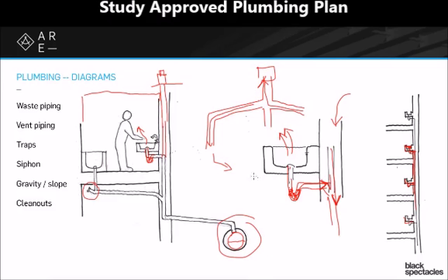that whole thing out. So at the bottom of all the verticals, at any major 90-degree turn or any other kind of strange shape in the pipes, even pipes that are straight but go for a very long way, you might have multiple clean outs along it, just so that you had the ability to figure out where there was a problem and to be able to get to it with a rodding system or whatever else you needed to do.